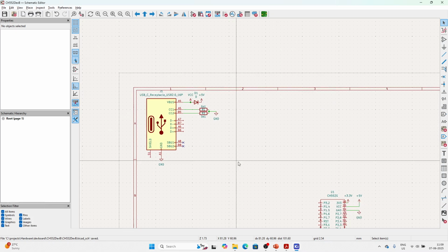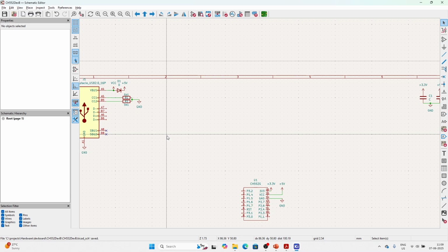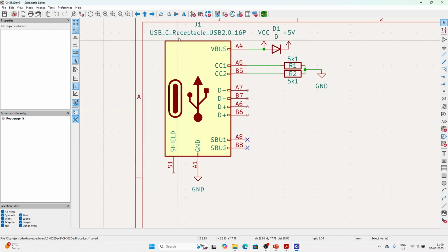So this is with respect to power delivery for this. How does it work? I connect my USB cable here. I'll have ground, I'll have USB power. There would be CC1 and CC2 if I'm using USB-C to USB-C, which would do the power negotiation with the other side and give us pure 5 volts here. If I'm just keeping this for namesake, even if it is not there, it works.